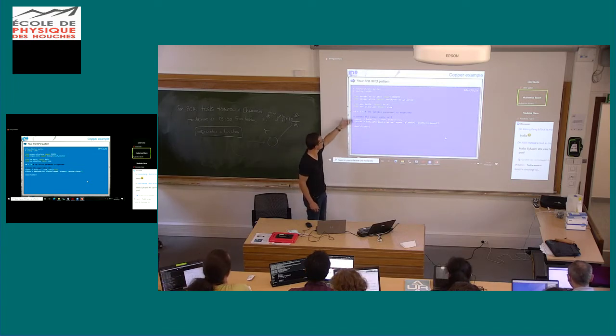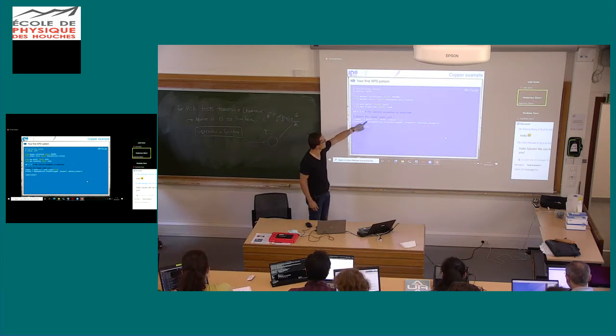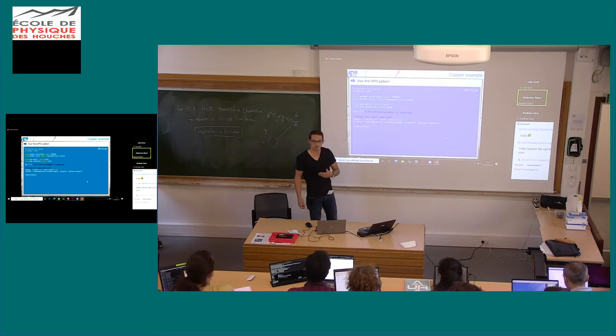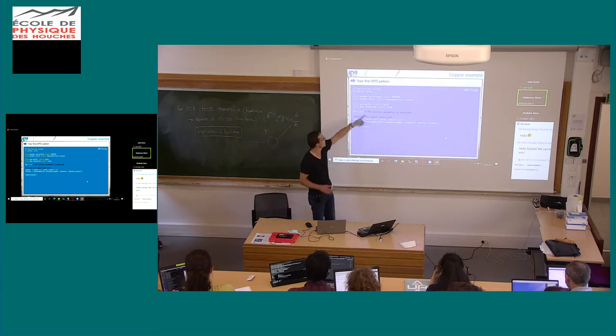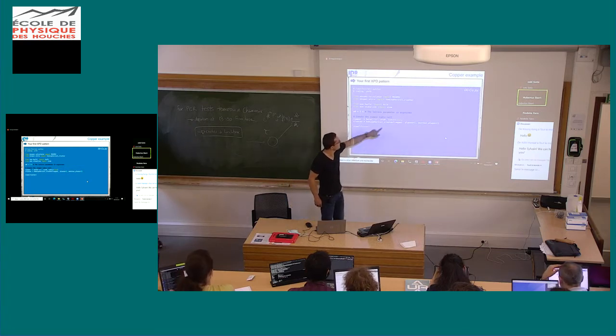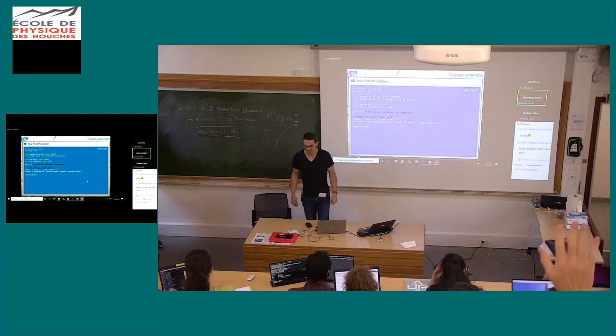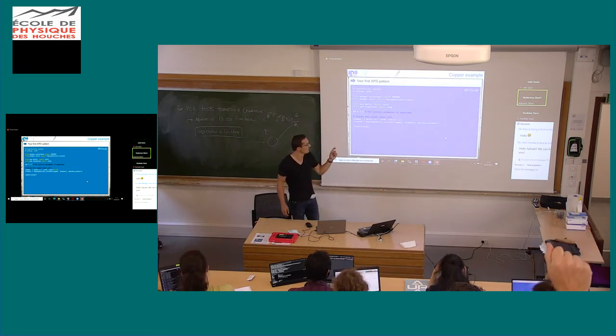And here are the lines. To create a bulk copper cluster, it is easy. The first line is to call the bulk function of ASE with copper as the element. ASE knows that copper is FCC, but you can specify another structure if you want. You can give it the lattice parameter if you want it to be different from the normal lattice parameter of copper. And finally, there is another keyword that is really important to us, which is cubic. It is a Boolean value.